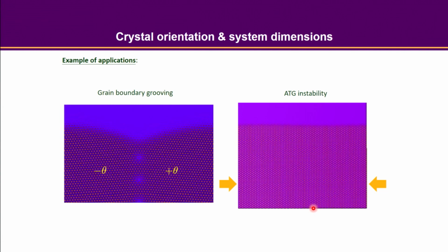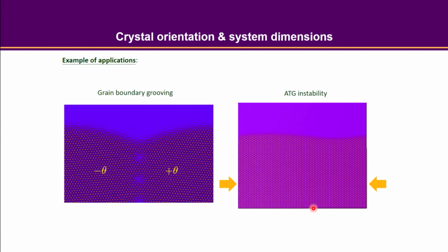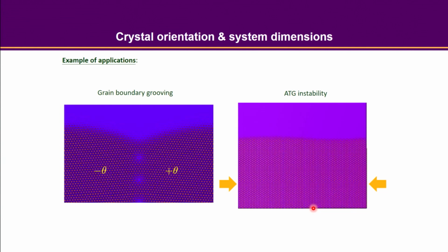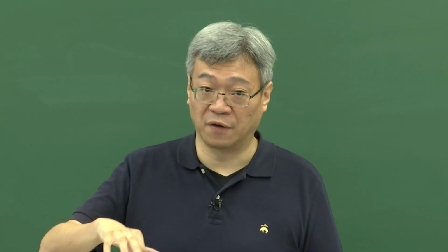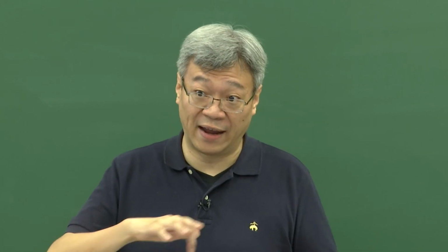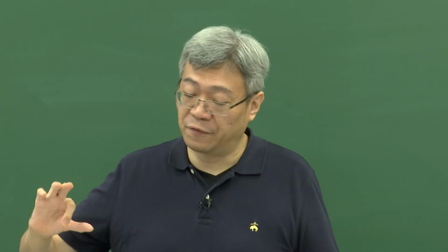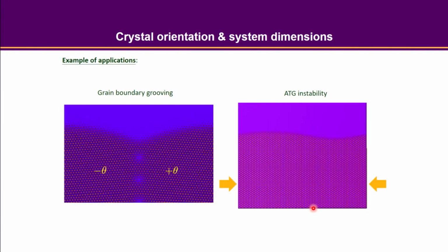So if, let's say, Lx is 100, but when I run the simulation the Lx is actually 99, the nearby atoms will feel the size being squeezed by 1%, right? And that kind of squeeze is going to increase the elastic energy of the system. But we know thermodynamically the system goes toward the free energy minimum if possible.